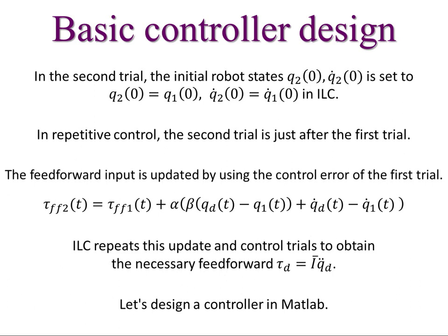To input the learned feed-forward torque to the controller block, let's add a tau ff to the input of the controller block. Let's add the error feedback to this tau ff to give the actuator torque tau. This part is the same as the computed torque method.